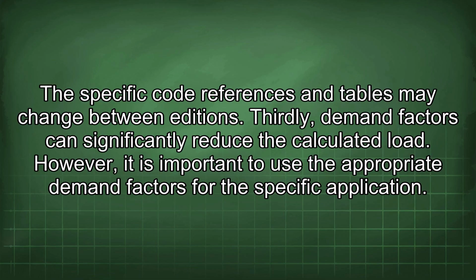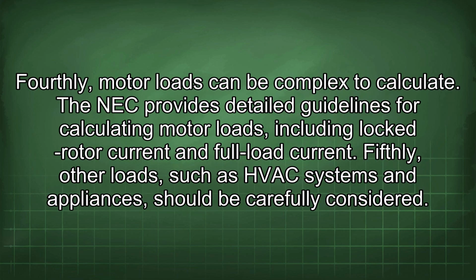Thirdly, demand factors can significantly reduce the calculated load. However, it is important to use the appropriate demand factors for the specific application. Fourthly, motor loads can be complex to calculate. The NEC provides detailed guidelines for calculating motor loads, including locked rotor current and full load current.